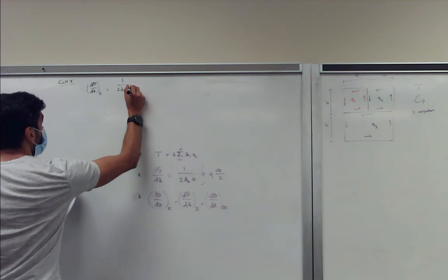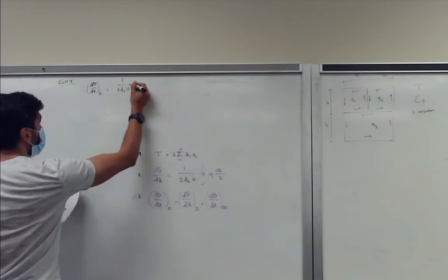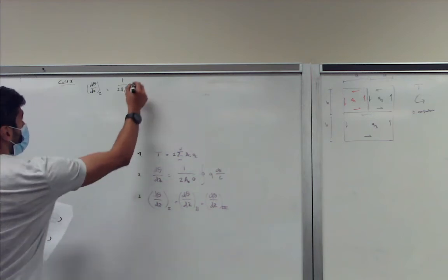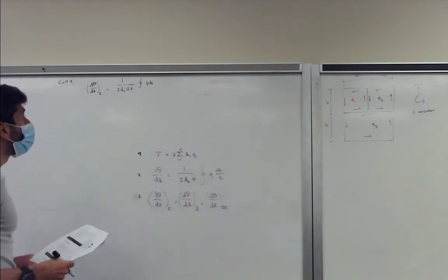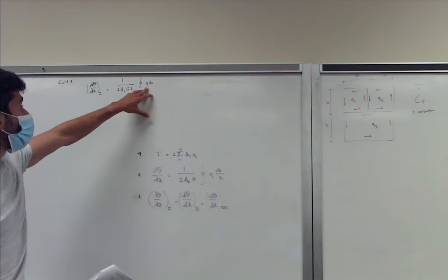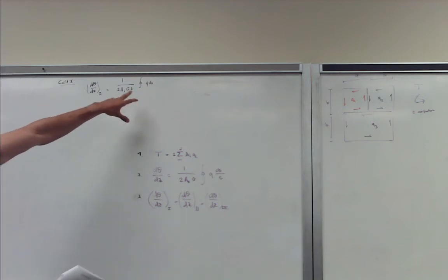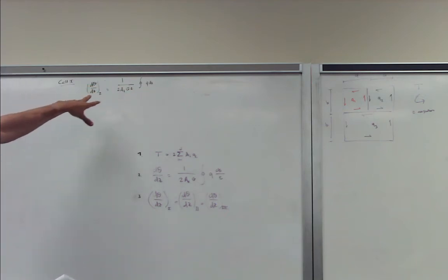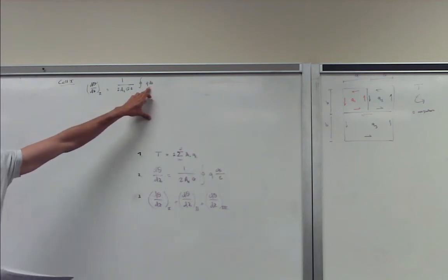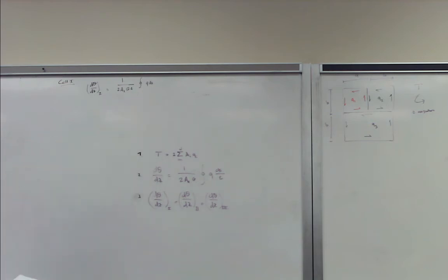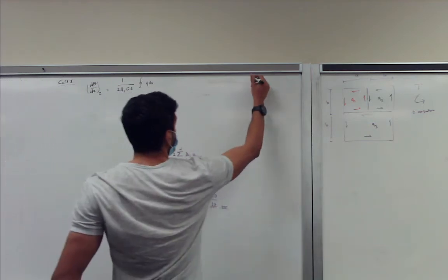And we also set t equal to t everywhere, so we can take that out too. Then we get the integral of q ds. What does this mean? This is the integral around the cross section of cell 1, and the ds part is nothing else than the total distance traveled, so segment 1.